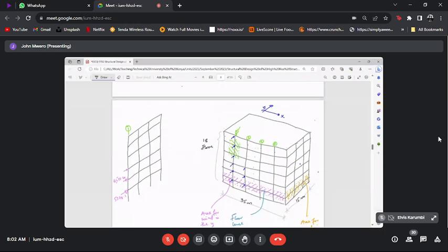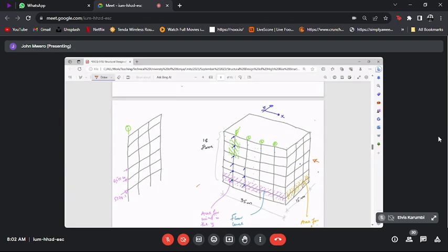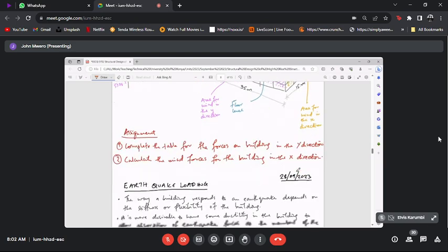If you try to push this, our hypothetical building, in that direction or in that direction, it's a lot easier to push it in that direction because it's slender that way and it's less stiff. It's more flexible that way than this way. So in an earthquake, a building like this would have a different vibration pattern, from your dynamics of structures, and by extension, different periods of vibration in one direction compared to the other direction. That's what that statement says.